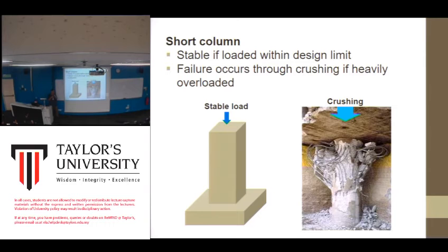But considering the safety factor, there's a calculation that I showed in the first or second week. Even though the load that you want the structure to carry is 10,000 kilonewton, the actual design of the structure should be more than that. It could be, let's say, to cater for 15,000 kilonewton, right? So there's a safety margin for that.